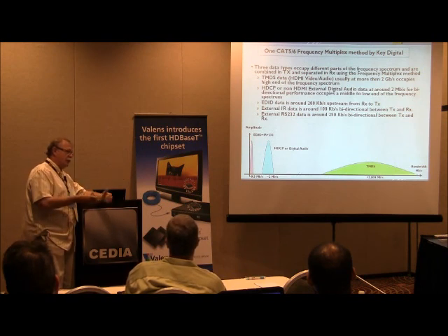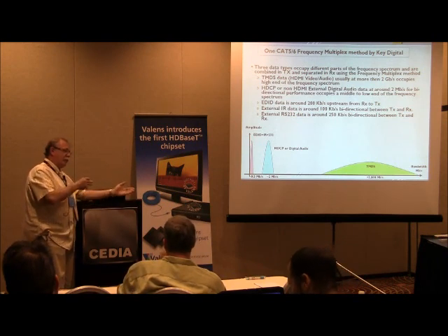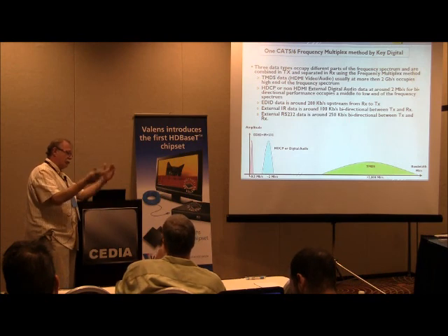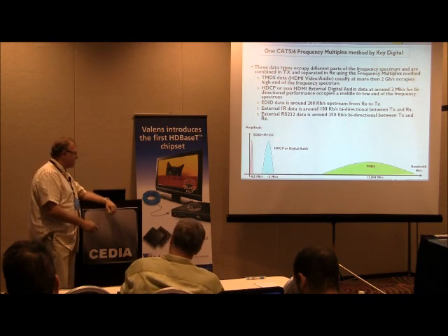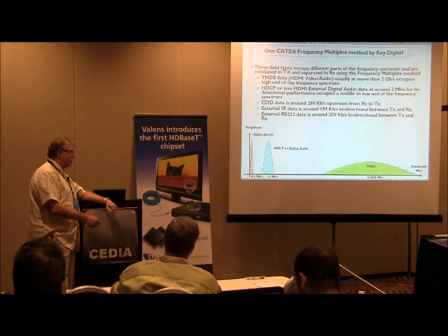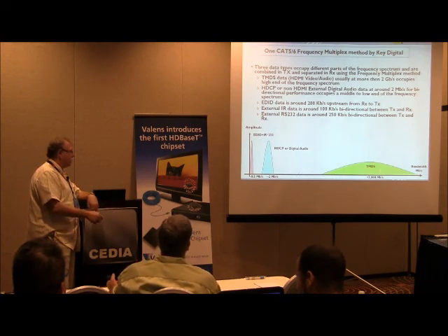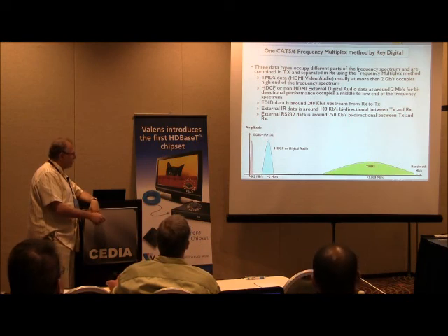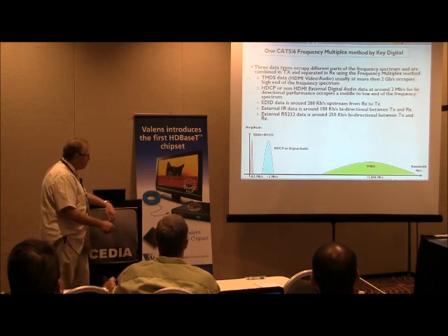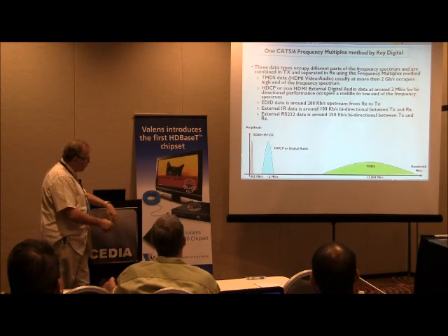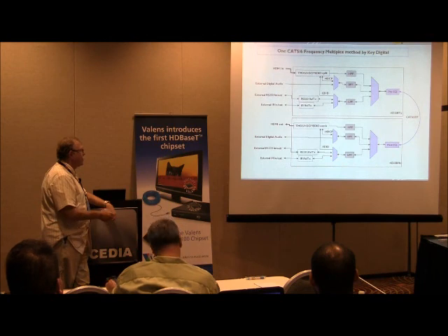Similar to what you have, let's say, in a cable TV system when you can dial different channels, channel 700, channel 50, channel 20. In this case, the high frequency channel is TMDS and the low frequency channels are digital audio, HDCP, EDID, IR, and 232. These signals, EDID, IR, and 232, can be combined together to form one channel. And HDCP or digital audio could also occupy a little bit higher frequency channel, but both of them can live together with TMDS on a single line. So we made this kind of a system.